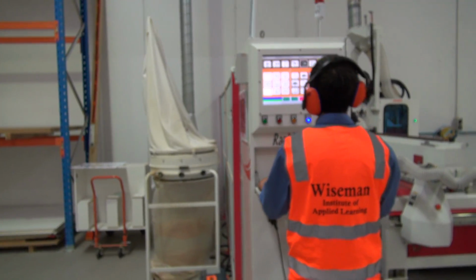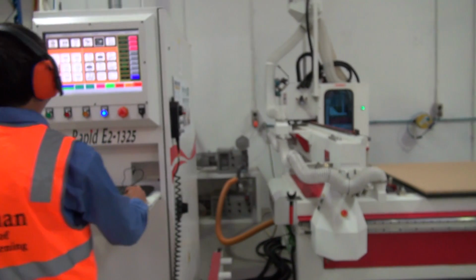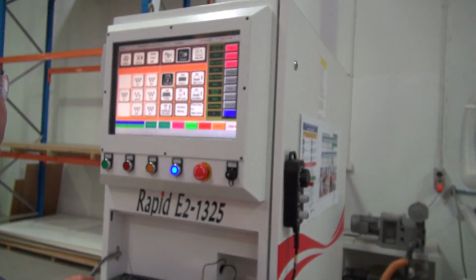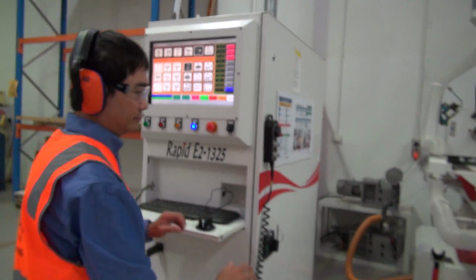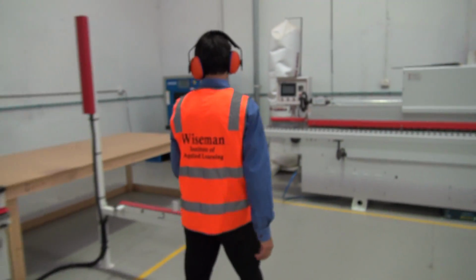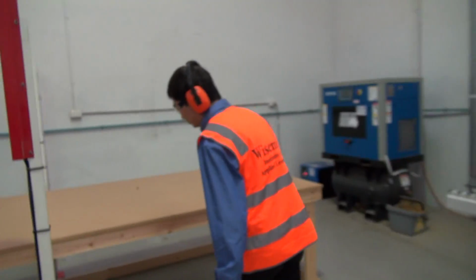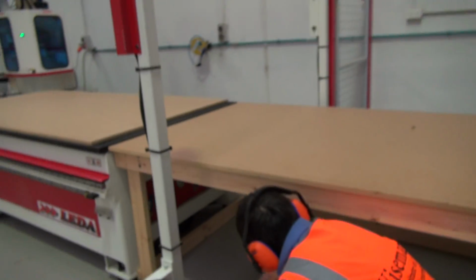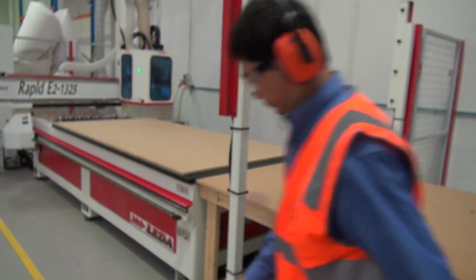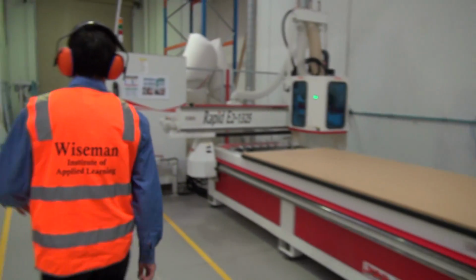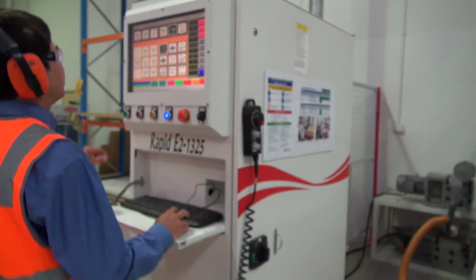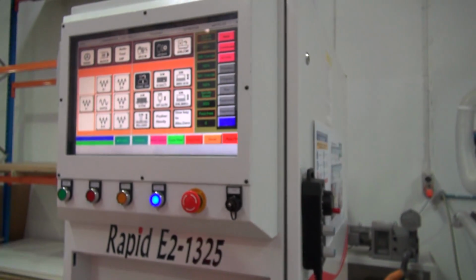The vacuum system on the CNC router has a direct impact on safety and quality. If the suction is not at the desired pressure or level, it could lead to small pieces being moved on the machine bed. Vacuum pump provides suction to the bed, securing materials. Vacuum sector control: if small sheets are being cut, the controls or handles on the side of the machine enable the user to turn off vacuum to designated parts of the machine bed.